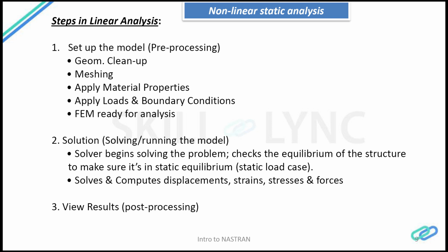First one is the cleanup of the geometry, and then obviously you have to build the finite element model, you have to mesh the model, and then you have to apply the material properties, loads and boundary conditions, and make the model ready for the analysis or for the solver to solve the model.